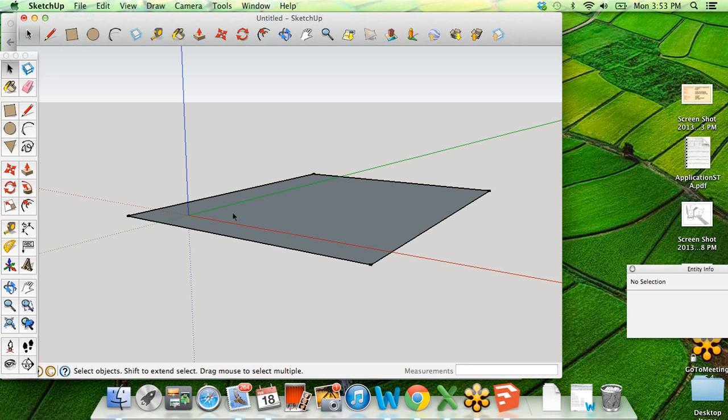First of all, it's surrounded by 4 black edges, and I can select those individually. So when you're building a rectangle, you're really building 4 edges, and then the inside is being filled in. That's important because you can do the same things with the edges of the rectangles that you can with the line or edge tool.